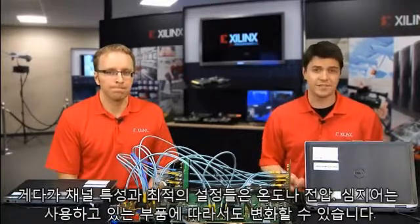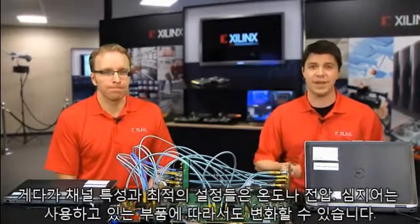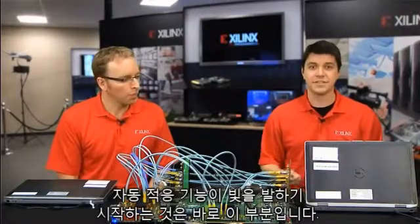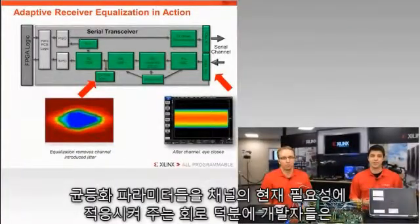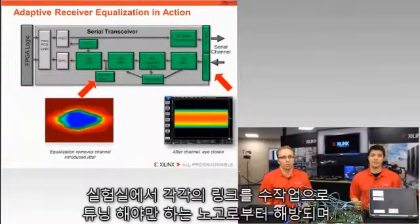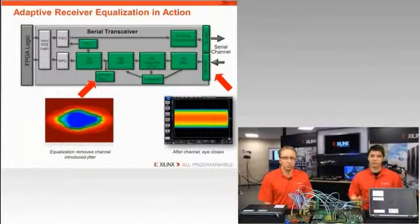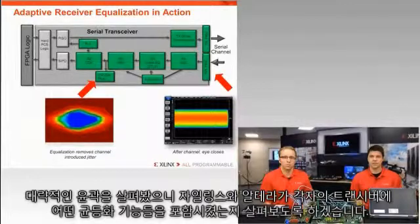Furthermore, the channel characteristics and optimal settings can change depending on temperature, voltage, or even the part that you're using. This is where auto-adaptation starts to shine. Having circuitry that adapts the equalization parameters to the current needs of the channel frees designers from having to manually tune each link in the lab, while ensuring that those settings are continually optimized regardless of the system's environment. With that basic outline, let's take a look at what equalization features Xilinx and Altera have included in their transceivers.